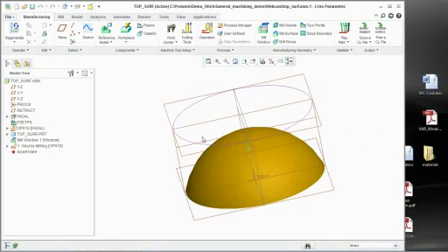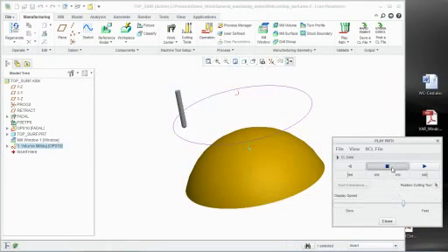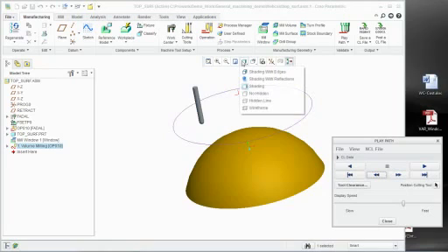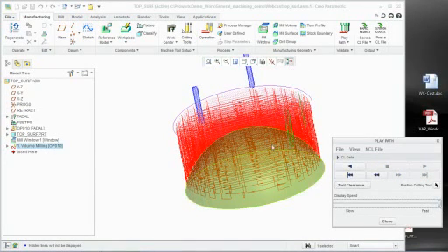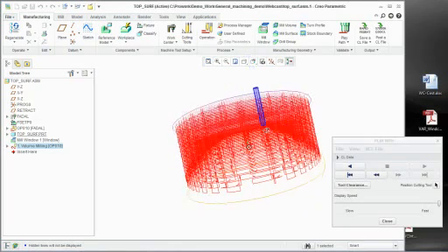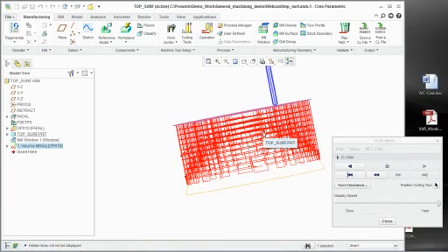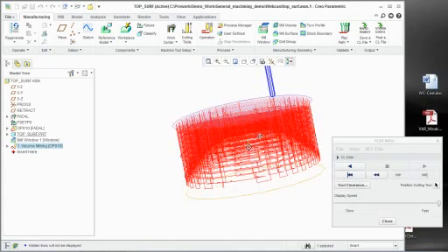All right. This one right here, what I wanted to show you is a typical voluming sequence that you would create. And hold on here, guys, let me so you can see this. This is a typical voluming sequence that you would create. And what you get here is a lot of airtime cutting if you are cutting castings. If you want to do voluming or hogging out type sequences, and you have just a casting or a ½ inch worth of something or a ¼ inch worth of something, you do a lot of air cutting in these situations.